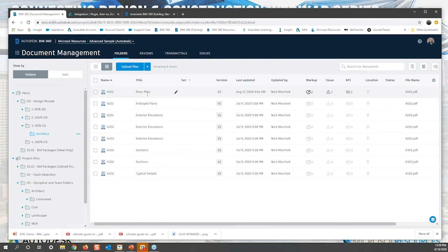You can define multiple categories that you want, and then as you bring in the rest of the sheets, you can say use this template, and it'll read that information for you, and it'll categorize it correctly and label it correctly in BIM 360. So it's pretty useful in the sense that it helps streamline the upload and organization process for you. It also helps make the search functionality that we have in BIM 360 much faster and more accurate as well.